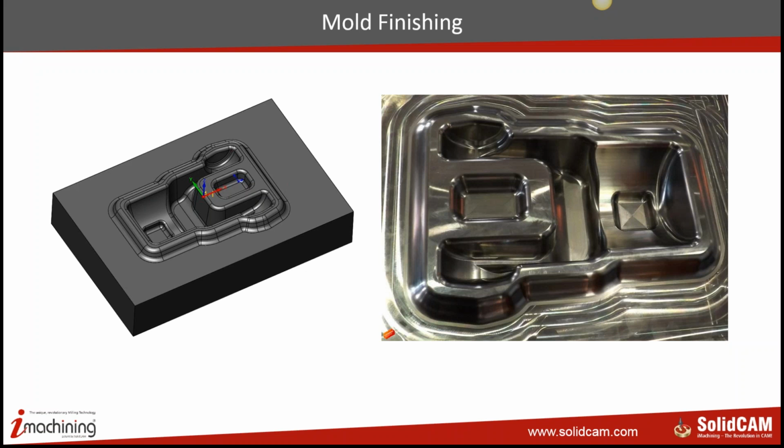That's because we have amazing control over what we are trying to do and how we are trying to machine a particular area. It's been my experience that whenever you machine a particular surface along its flow lines, along the U and V lines, you always get an exceptional surface finish.